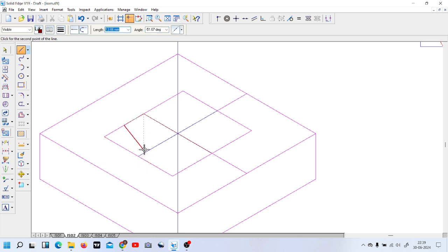Minus 150 angle. Connect over here. Similarly, from this end point, you just draw 10 mm, minus 150, or 20 mm. Just delete it. On this side also you just draw half distance. There is 10 mm and you connect over here, and from this side you just draw 10 mm, at an angle of 30 degrees, and then you connect over here.